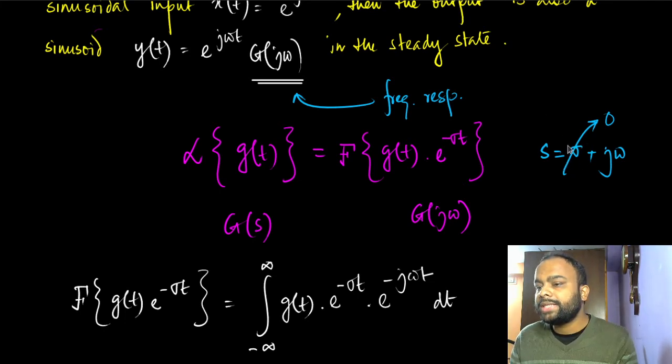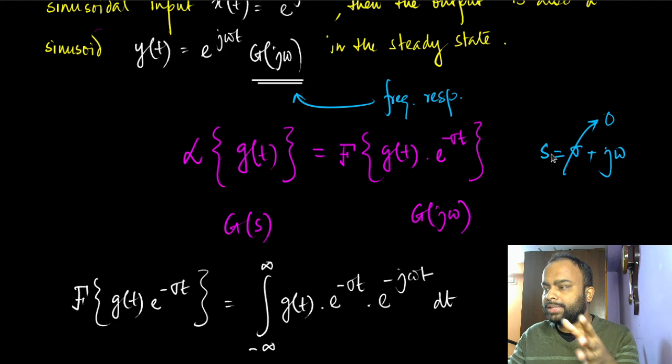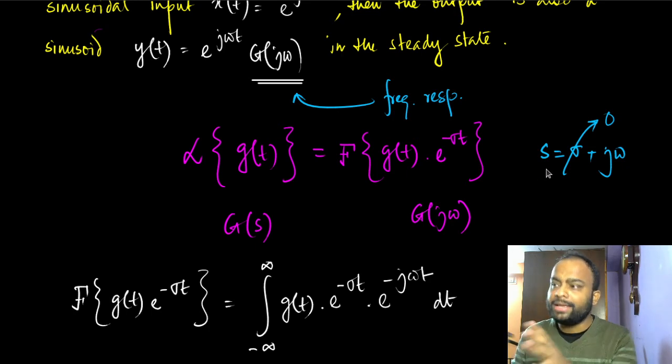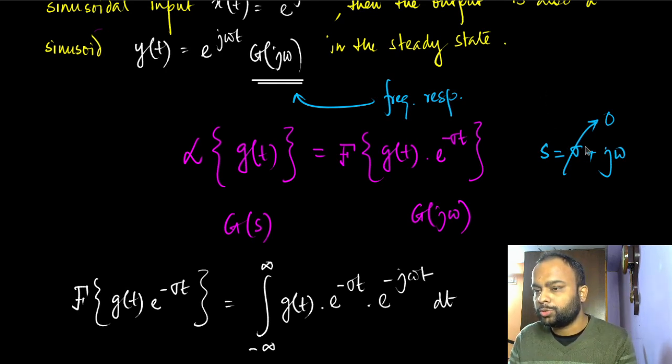We will see that this sigma will appear on top of real exponents, and there will be other things multiplied with those parts. For stability, all these sigma values should be negative. The real parts of the pole locations should be negative. So essentially I would have negative sigma values, and all those exponential factors will become zero as time approaches infinity.